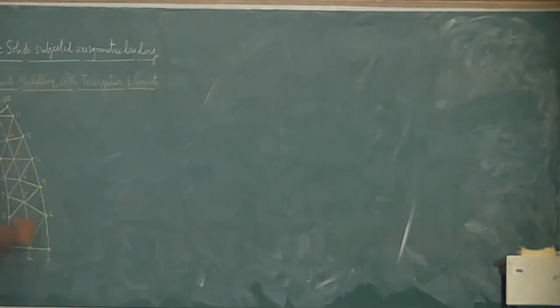The complete thickness of the wall of the shell, that is the solid of revolution, I will convert into a 2D section. Always remember, there is an axis here, and this is going to be your R axis. This is R and this is Z. So I have taken this particular segment and divided it. Let us give the element numbers 1, 2, 3, 4, and the fourth element, then 5, 6, 7 and 8.